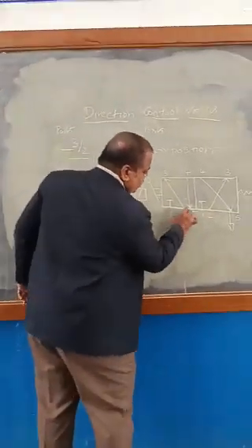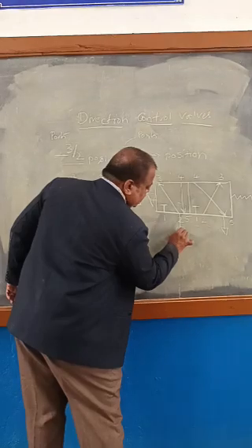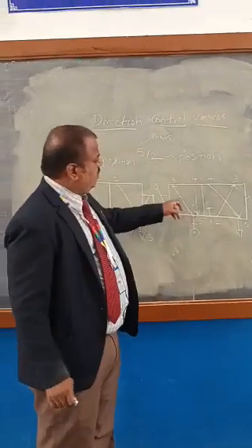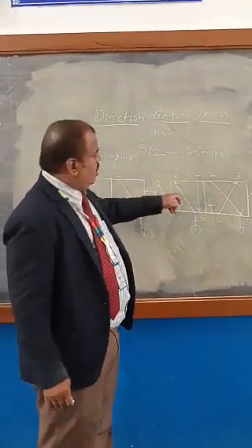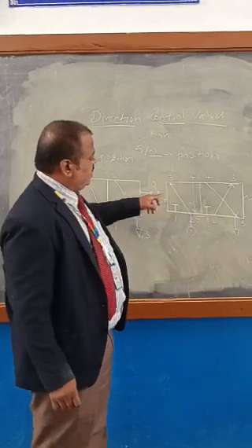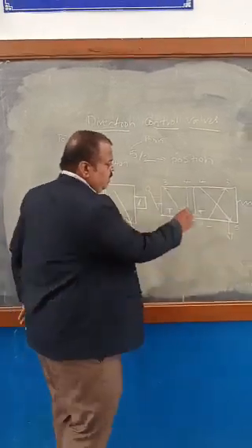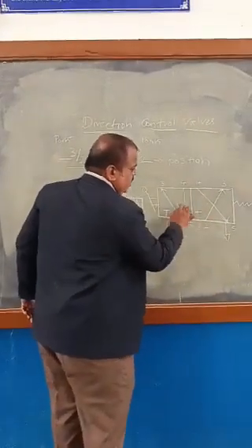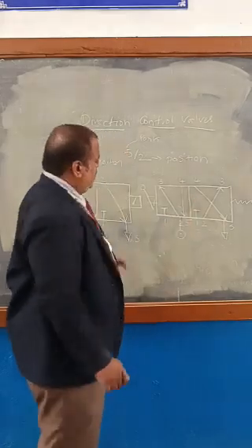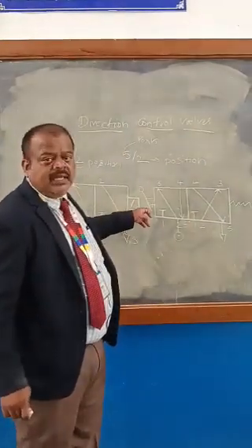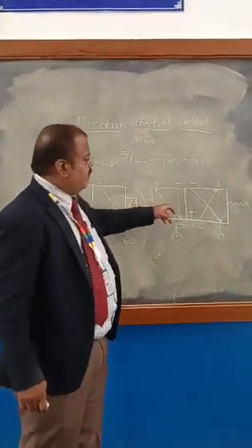Okay, from the second port, here we will be having a compressor or a pump. It sends a pneumatic fluid like air or working fluid to the system. And this 5x2 direction control valve is separated, so this is 2 position, 5 ports. And this symbol represents the hand lever. It is a hand lever operated valve.